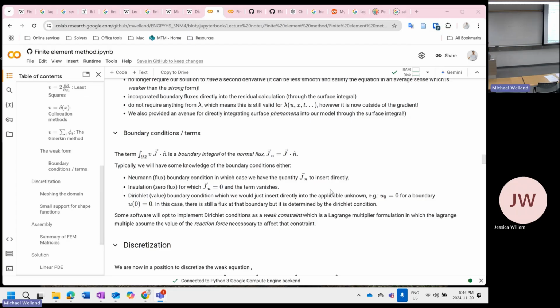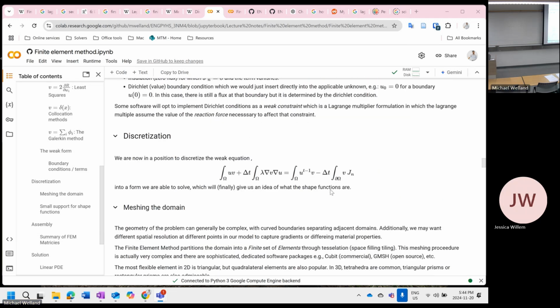In this context, that means that's your heat flux at the boundary. So it is the heat flux which is required in order to keep the temperature at that value. Why that's useful is because if you really wanted to know with super high accuracy what that heat flux should be at the boundary, and there are a lot of cases where you would want that, you use that as a Lagrange multiplier and then you can calculate it directly. And it's a very accurate answer. But generally you don't need to.